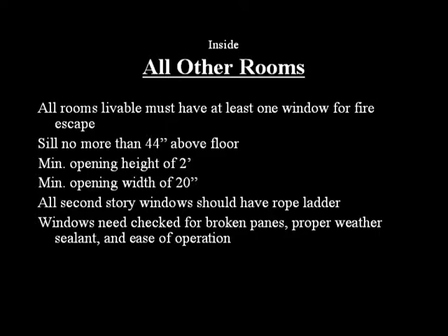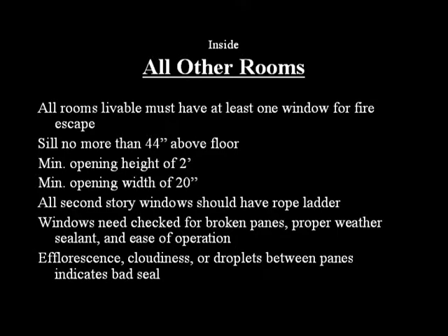Windows should be checked in every room for broken or cracked panes, proper weather sealant, and ease of operation. In our window lesson earlier, we learned that efflorescence, cloudiness, or water droplets in between the panes indicates a bad seal.